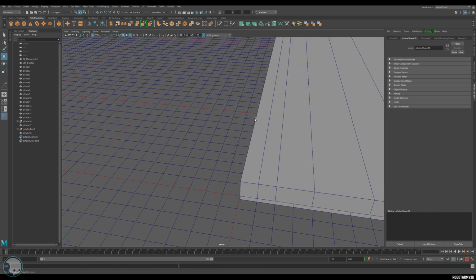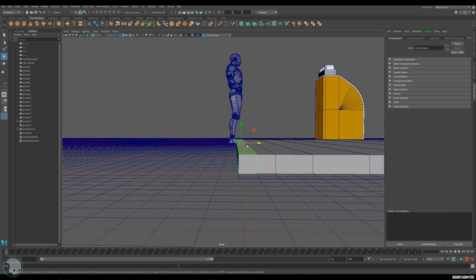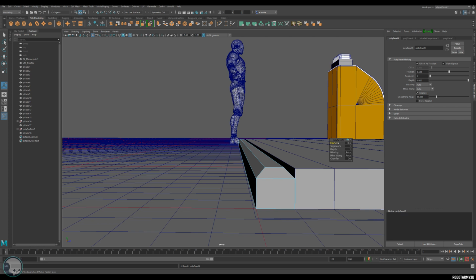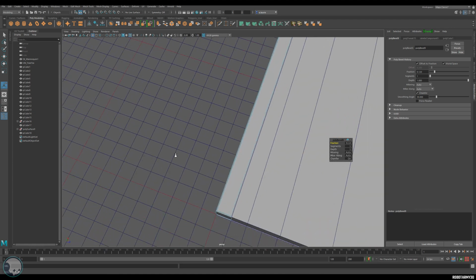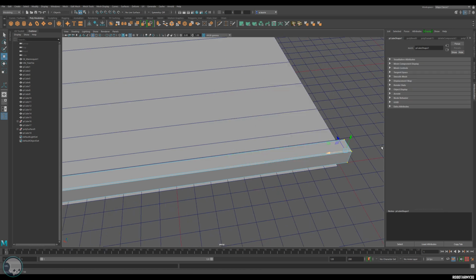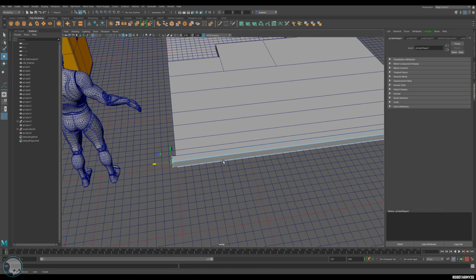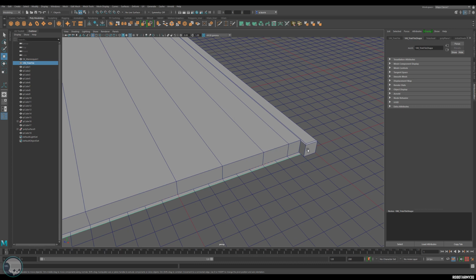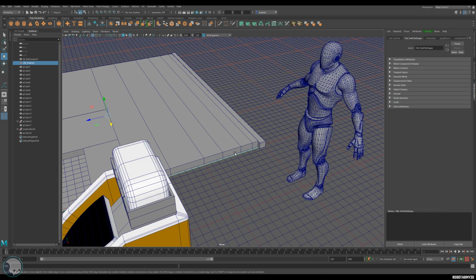So what I'll do is this first piece here is going to have beveled edges. I'm just going to grab the top, go Control F10, and then bevel these edges. Just have a small bevel on that, 0.12. And I'm going to make this one so that it tiles endlessly. So all I'm going to do is grab this edge and drag it off like that, so that it becomes outside the bounds of the projection in Substance Painter. Because this is one-to-one on the UV grid, this is outside that UV grid and outside the edge of this. So we will get no baking or edge details on this. It'll seem like it just carries on forever. The normals will carry on flat, and there won't be any ambient occlusion or anything on the edges there.